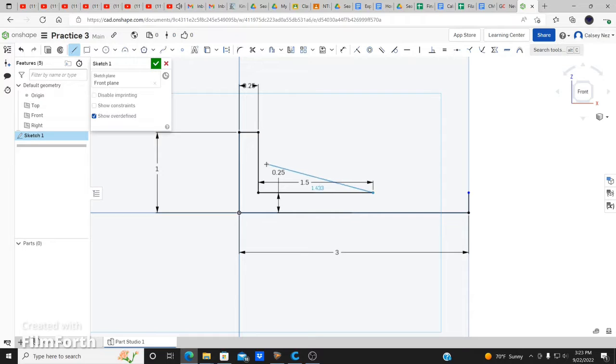If I go over here to the center of this line right here and bring this along, you guys see a yellow hidden line, and it'll give you the exact same height. Some of the other software will have that too, but they'll indicate it a little differently. Like they'll have a blue hidden line, a gray hidden line, etc. Now for this one right here, we're going to go to the end of this point, this edge or the corner, bring it out here, and it'll activate that secondary hand. And once you've got that, it'll be perfectly vertical and perpendicular.